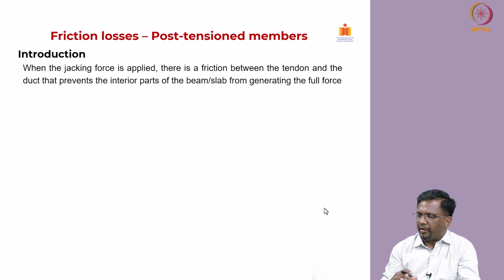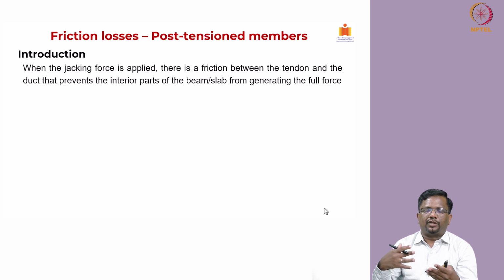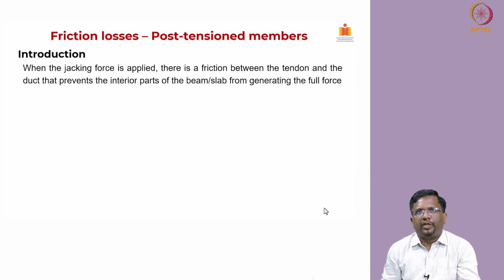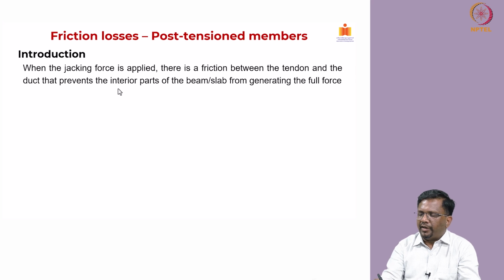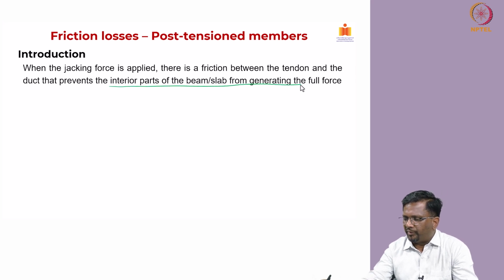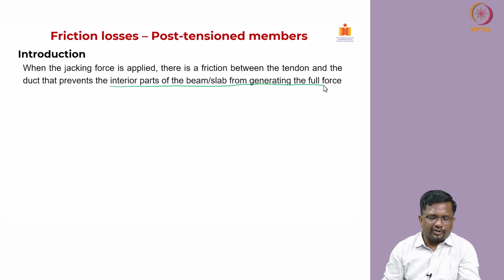But here when you do the stressing process, whether it is grouted or ungrouted, that will happen at a later point. When you do the stressing, the tendon is going to go and rub against the surface of the duct, right. So that will prevent the interior parts of the beam or slab from generating the full pre-stressing force, right.